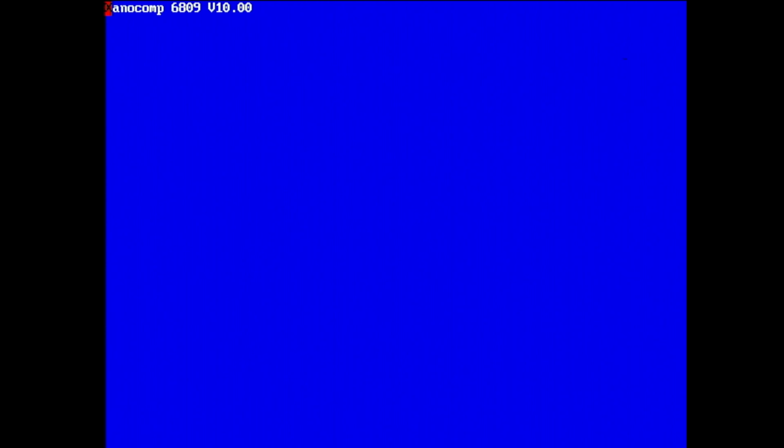Probably need a bit more buffering because they seem to be getting a little weak, and that seems to cause some interference sometimes. So that was the character mode, so there wasn't any of the red update that we saw previously. This is the black and white high-res 2-color mode, and you can see here that we've just got the 8-pixel line at the top, and we're not seeing the lines flash across the rest of the screen.